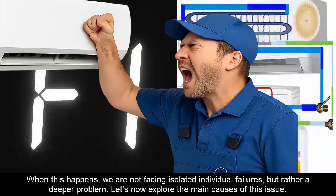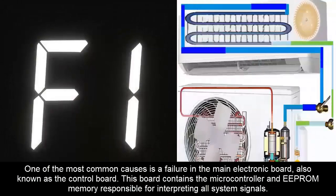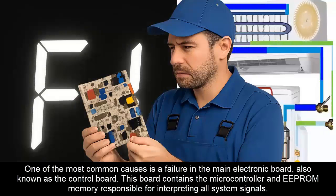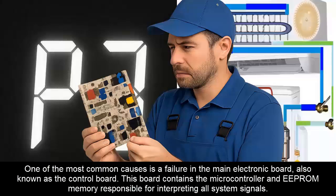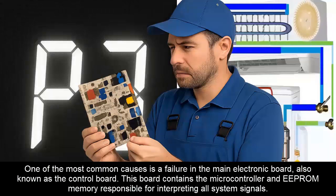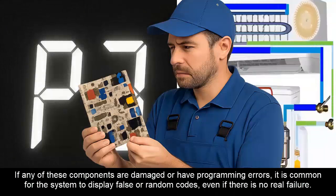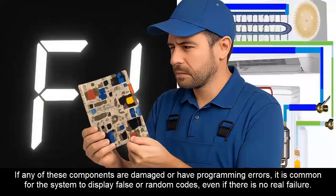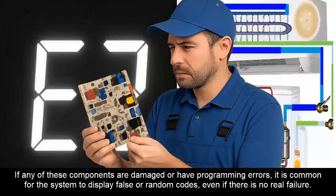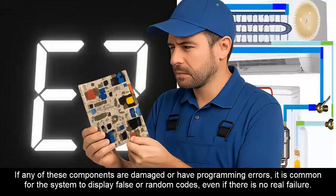Let's now explore the main causes of this issue. One of the most common causes is a failure in the main electronic board, also known as the control board. This board contains the microcontroller and EEPROM memory responsible for interpreting all system signals. If any of these components are damaged or have programming errors, it is common for the system to display false or random codes, even if there is no real failure.